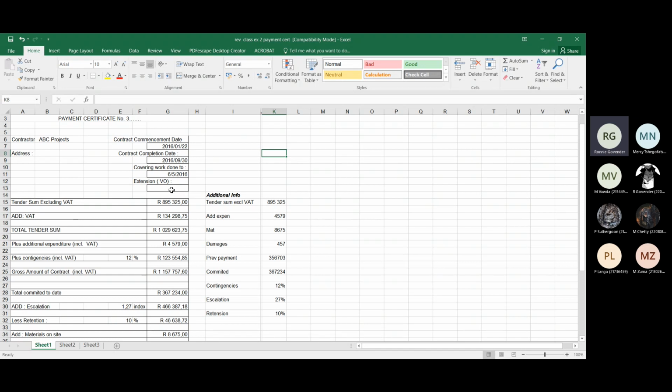You'll just sign a VO, the date, and you'll say contractor agrees to relocate pipe at an agreed amount of 5,000 Rand or whatever the case may be. And the contractor and you sign, he gets a copy. One goes into the file, the contract file, and one normally stays in the book itself for further reference. Right. On this particular contract, we're given additional information.